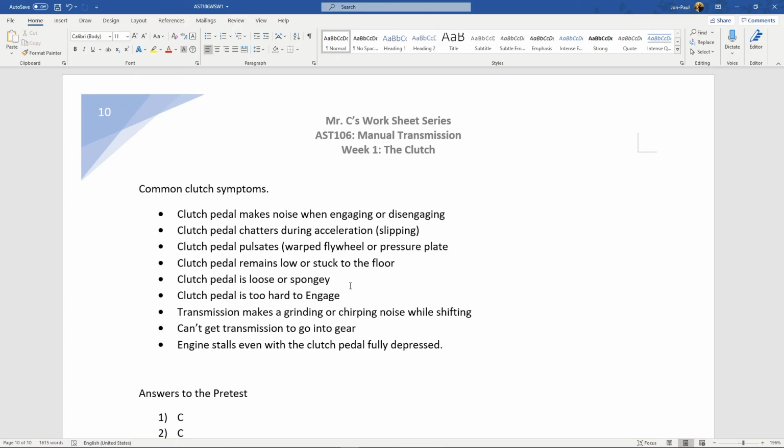If the circuit is functioning as it should, you will see the release fork travel the full distance of 3 or 4 inches. If there's air in the line, Jose's pushing the pedal all the way to the floor and it's compressing that air. It's not going to move the release fork very much. You'll be able to see it. It'll be cake. All right, do I need to go diagnose this or that? Cool. I've made a decision within just moments. So don't get hung up, don't get scared about this.